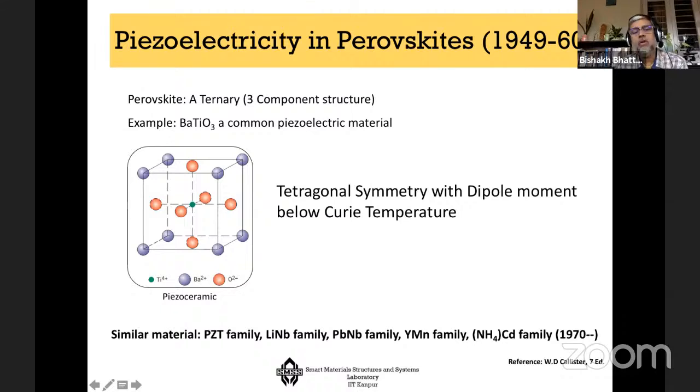Now, such a system, even though it is in electrical equilibrium, the moment you apply a little bit of pressure, this titanium at the center will get displaced a little bit. And that little displacement will create polarization in the system, because the electrical equilibrium will be lost, and titanium is very strongly electropositive. So it is going to be closer towards some of these anions, and as a result a charge will be instantly developed. So there will be an instant polarization in the system.